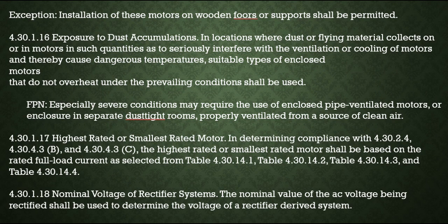This section outlines specific guidelines for motor installations. It permits motor installation on wooden supports for dusty environments. It mandates enclosed motors or specialized ventilation systems. Determining motor compliance involves referencing rated full load currents from specified tables. And also, it states that the numerical AC voltage should be used to determine the voltage in rectifier systems.